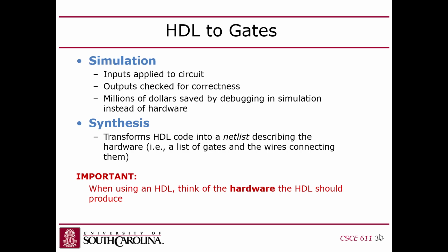But if you simulate, you can look at all the internal signals you want, because they're all being simulated. They're all virtual. So you can drill down into your design and see what's going on under the hood. But once you put it into hardware, it's sort of closed off. Now there's a way you can put probes, JTAG probes in, boundary scan probes, but every time you add more probes, you have to resynthesize, and it's not practical to do.